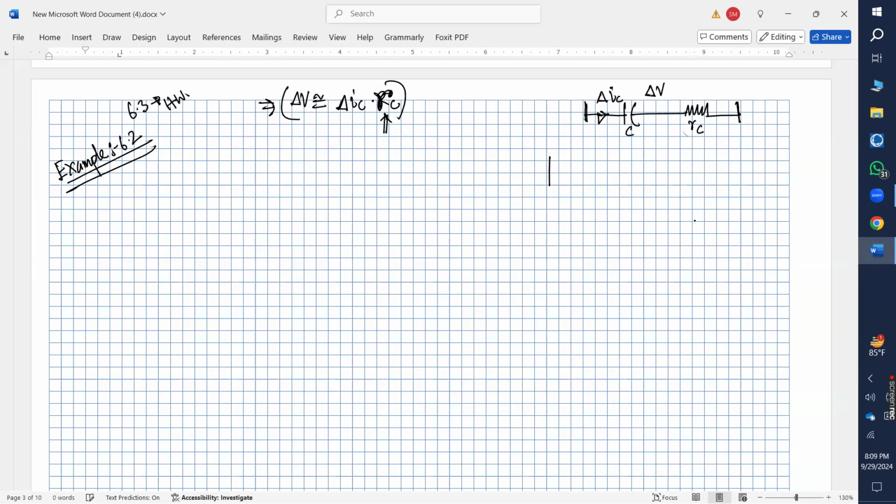So suppose, okay, somebody raised their hand. Can you tell me the question you have? Sir, in the diagram, did we consider RC as the internal resistance of the capacitor, not the external one? Okay, whatever ripple you will find across the capacitor, this resistance will be contributing to that. This delta V is the voltage drop.